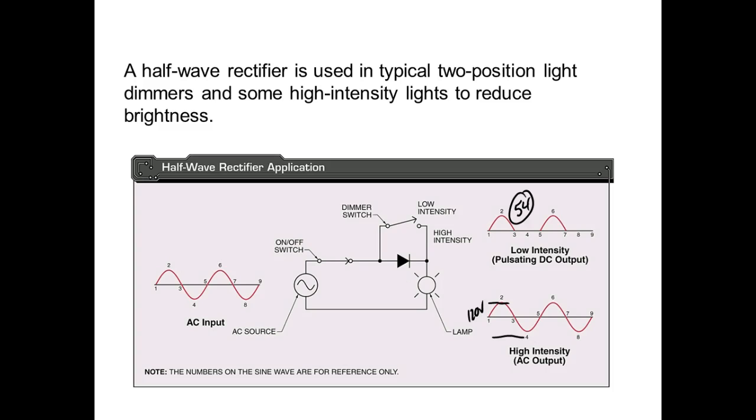I hope people understand that. Remember, power varies with the square of the voltage. So if this was a 100-watt light bulb, and I put 120 volts on it, then I would be equal to P over V. So that's 100 watts divided by 120 volts. That's what the current would be. So what would the current be? Okay, 0.83 amps.